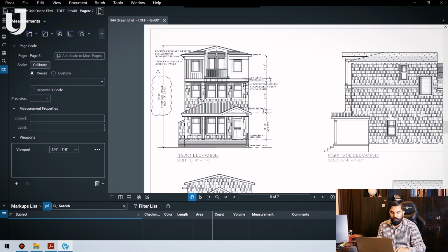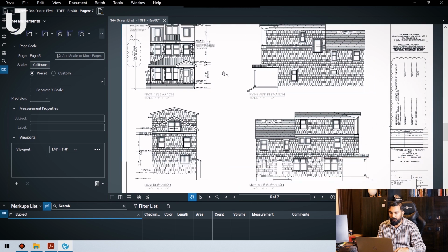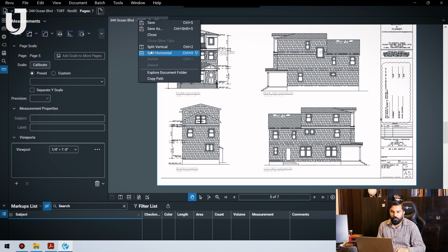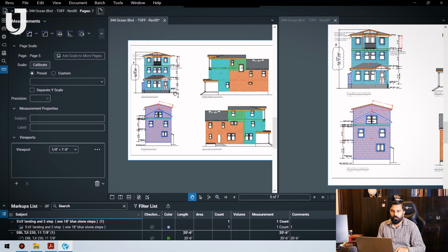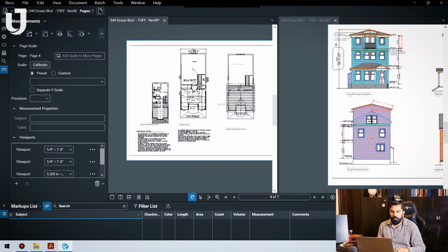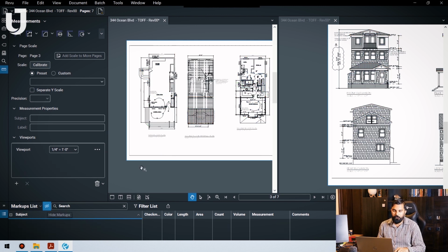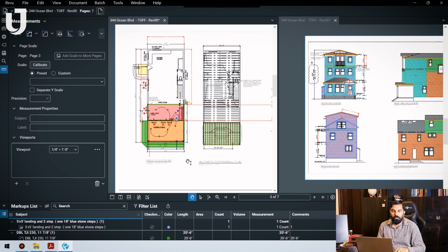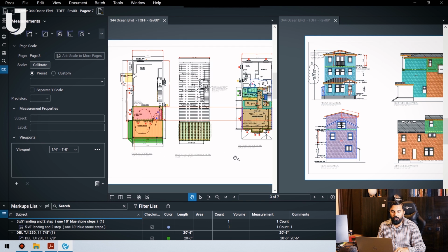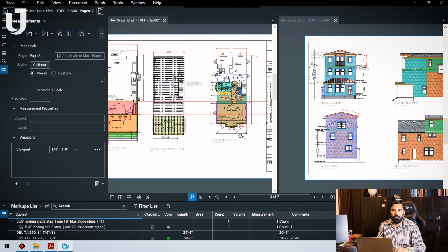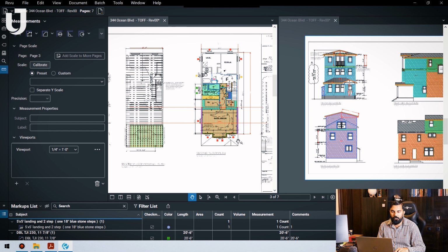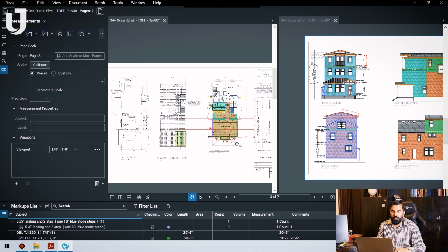So in this elevation, this is front elevation. Things are pretty clear. On the right side, this is the left side and the rear. One advice that I would like to give over here is, always, at least once you read the drawings, correlate your floor plan to the elevation to get the exact idea of the elevation. Sometimes there are returns that are hidden in the elevations that we cannot see in the elevation but are clearly visible in the plans.